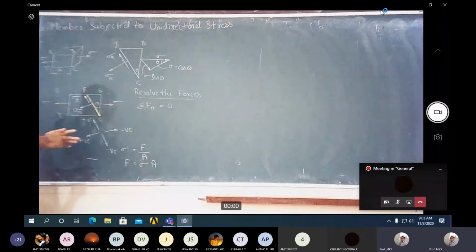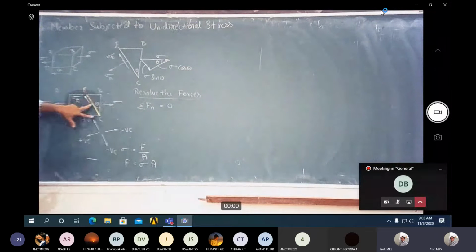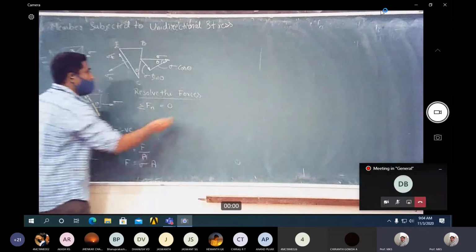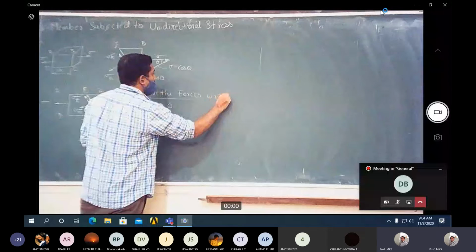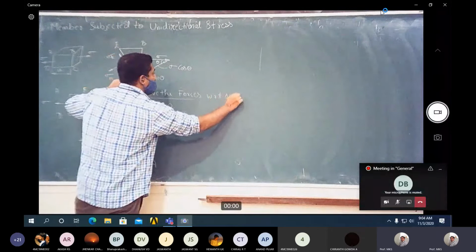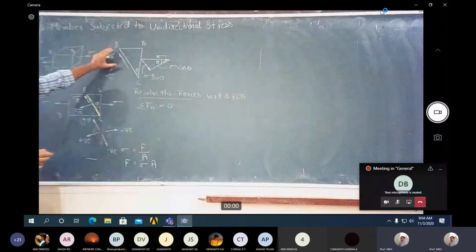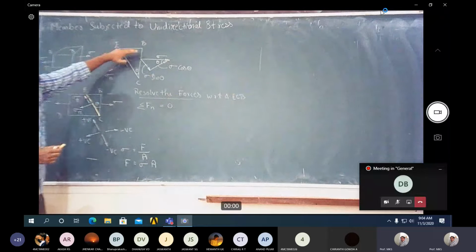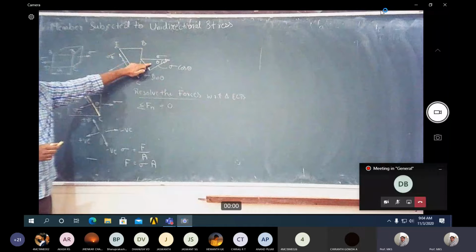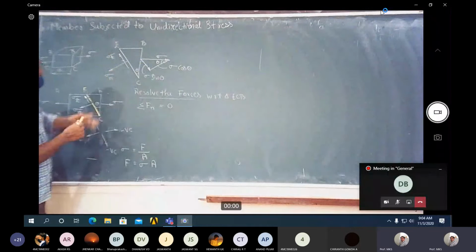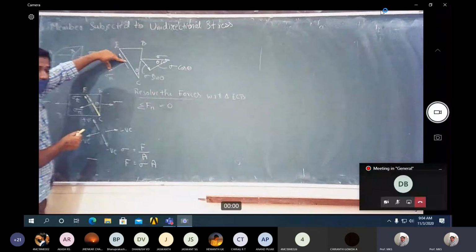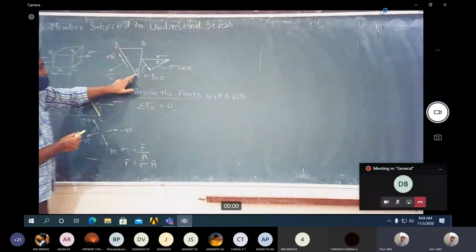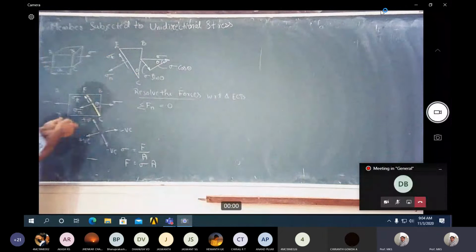Now I need to consider the plane EC, wherever I am going to resolve the force with respect to this triangle ECB. On the plane EC, we have the force acting. On the plane BC, we have the force acting, right? So the normal force on the plane EC is what? Sigma n, right? And its area is EC. Thickness is 1, we have considered it as unit thickness.